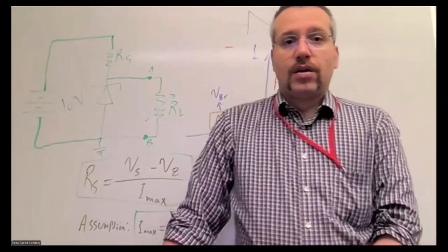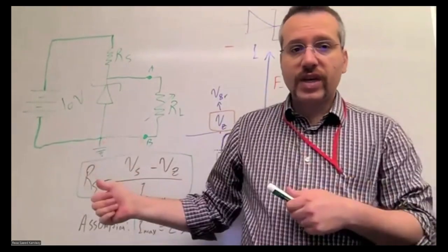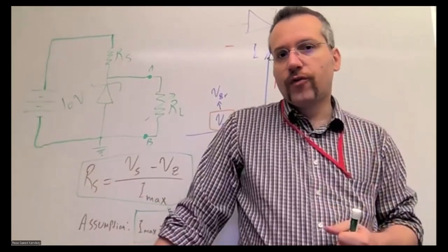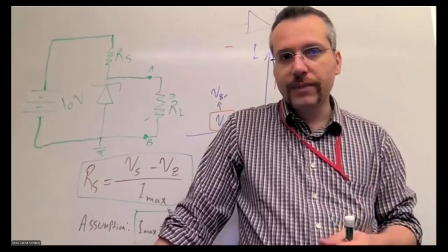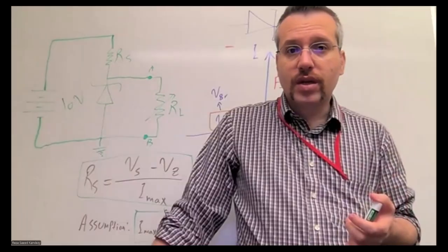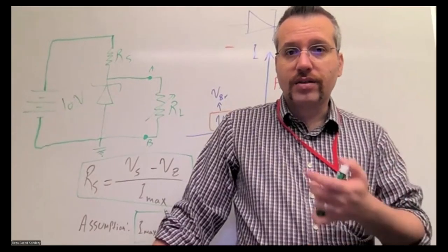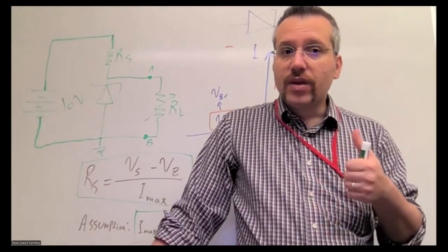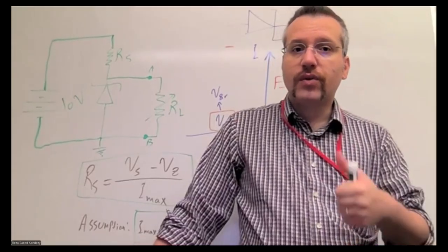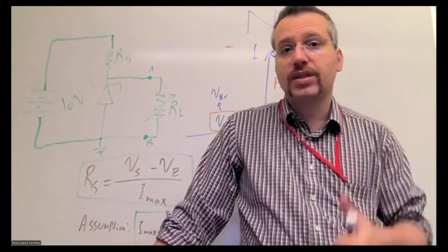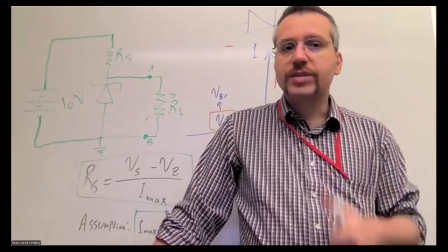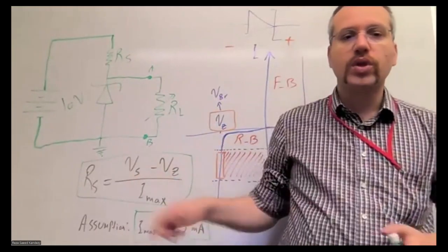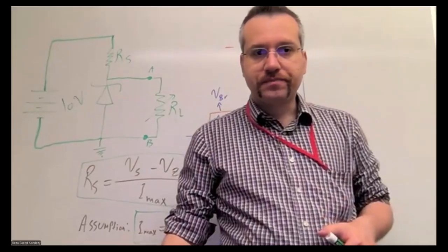Now, in our specific example, the Zener diode has a breakdown voltage, or Zener voltage, of 4.7 volts. Which means once the voltage across the Zener diode reaches 4.7 volts, it will start conducting in reverse and basically clamp the voltage. This keeps the output voltage stable even if the input voltage or the load has a variation.